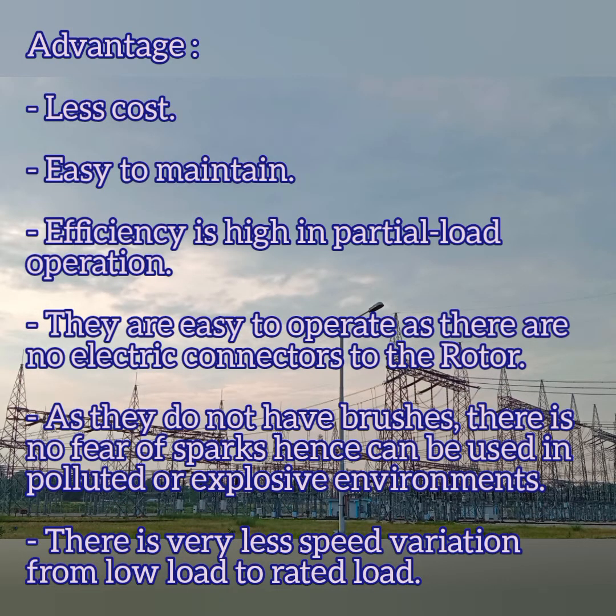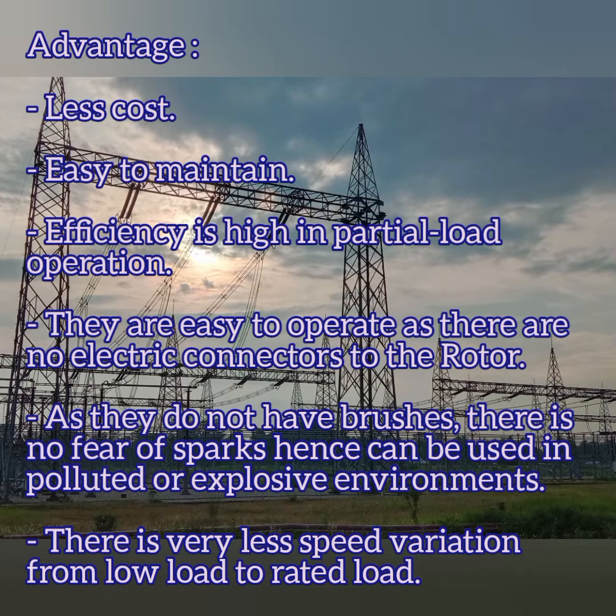Then the advantages of your asynchronous motor: it is low cost and easy to maintain. Then the efficiency is high in partial load due to their load dependence. If the load is less, automatically the efficiency of your motor will be higher. Then they are easy to operate as there are no electrical connections to the rotors. As there are no brushes, we don't need to care about sparking and explosions in the environment. Then there is very little speed variation from low to rated loads.